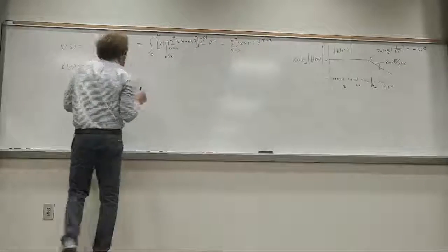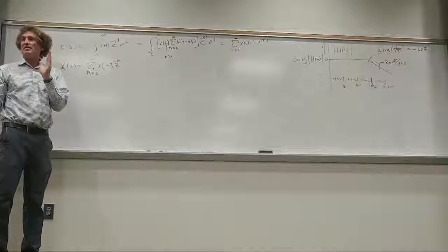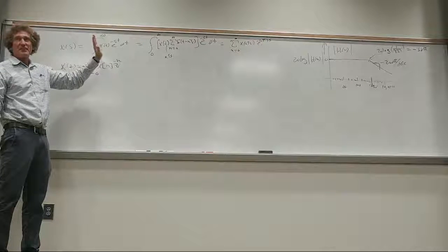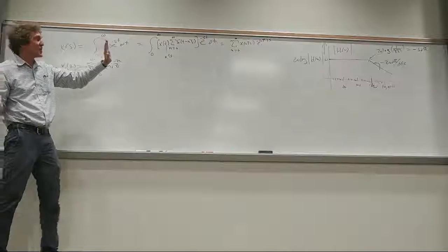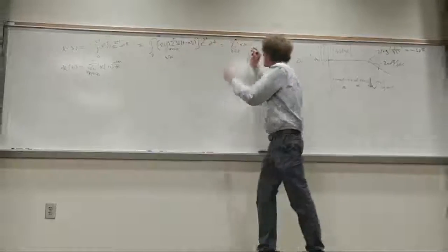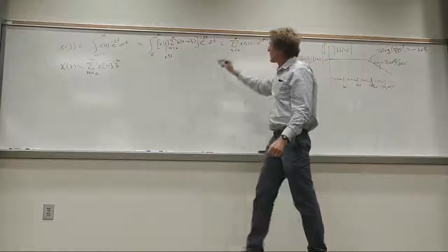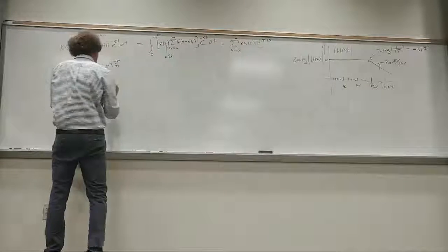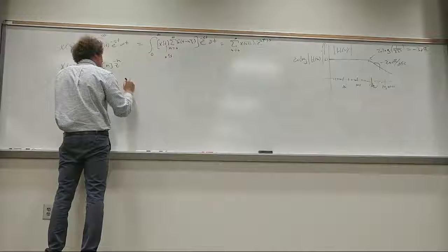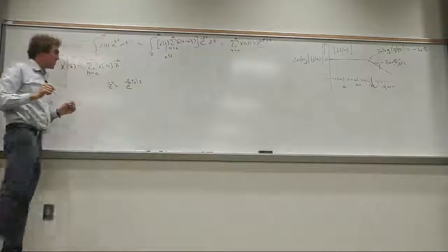At this point, without spending a lot of time on it, I want you to just understand something. There's something else that I'm not saying about this, because I'm trying to just focus on the bilinear transform. If you look at this for a second, you'll notice this and this are identical. Remember, with the n in there, we suppress the Ts. So this would have to equal this. That means I have z to the minus n is equal to e to the minus nTs times s. Are you with me?